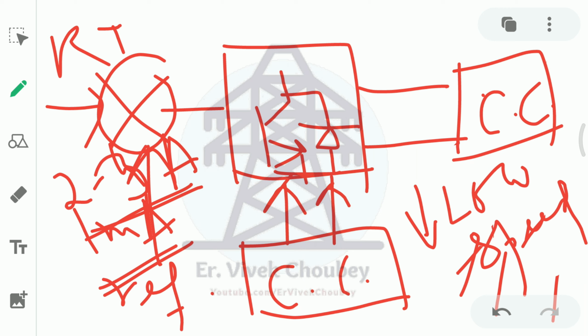So in an inverter AC, what happens? This current is taken only once. Okay, like a huge amount of current is taken only once by the induction motor of the compressor. That is only during the start. And in between, even if there is same temperature, or even the temperature difference between the reference and the room temperature is 0, what happens? The compressor keeps on rotating at a certain speed, and in that way, what happens? The average power consumption by the AC is low. Okay, so it helps in saving money as well as environment as well as electricity. So it's an efficient technology.